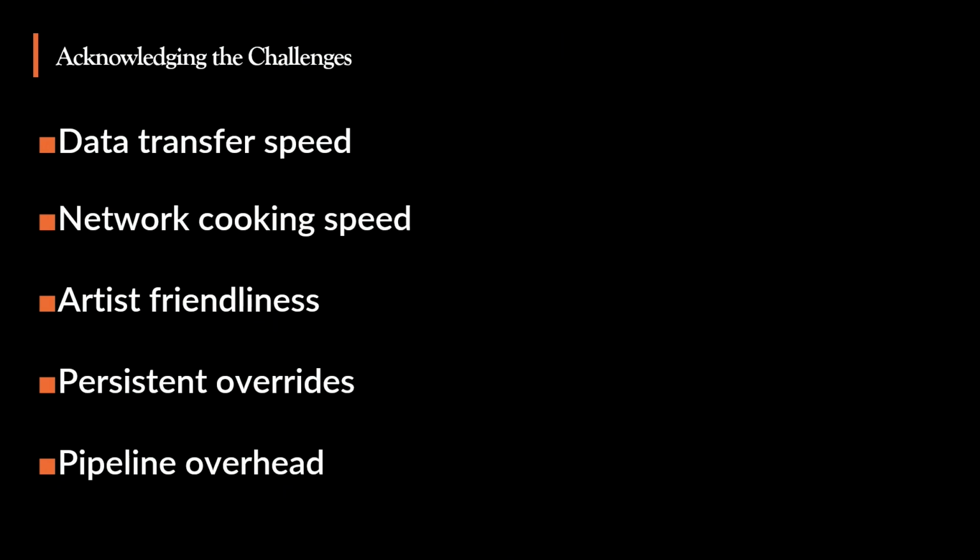Our plugin team has been working very, very hard on this and improving how they build Houdini Engine, how they structure the memory sharing, the communication. So it's getting faster. But also people have their custom solutions. Maybe they don't necessarily go through Houdini Engine. They can go through a custom JSON format or some other CSV format to bring the data in. What I'm saying is that there are solutions to this. It's not a deal breaker. A second thing, if you feel like your cooking is taking too much time, there might be opportunities to optimize your SOP network or your PCG network. Just do the design of the tool better, and it's also not a deal breaker.